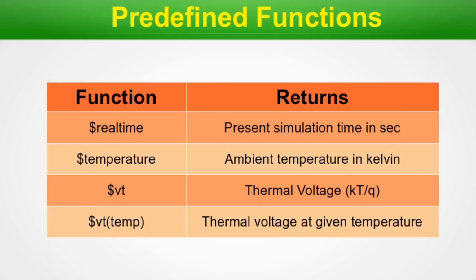Let's move on to predefined functions. Verilog-A has some predefined functions like $realtime. It returns the present simulation time in seconds. $temperature gives the ambient temperature in Kelvin. $vt is the thermal voltage kT by q, and $vt with a temperature argument is the thermal voltage at a given temperature. So these are predefined functions.